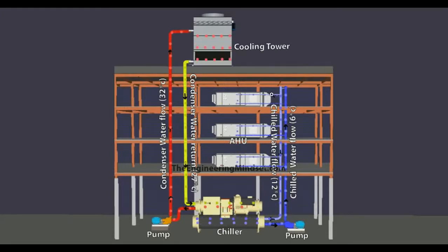And this heat is then returned back to the chiller, and it's returning here at about 12 degrees. By the time it leaves the chiller again, it will have given up 6 degrees Celsius worth of heat, so it's leaving at 6 again. So it leaves at 6, comes back at 12, and this cycle repeats and repeats.